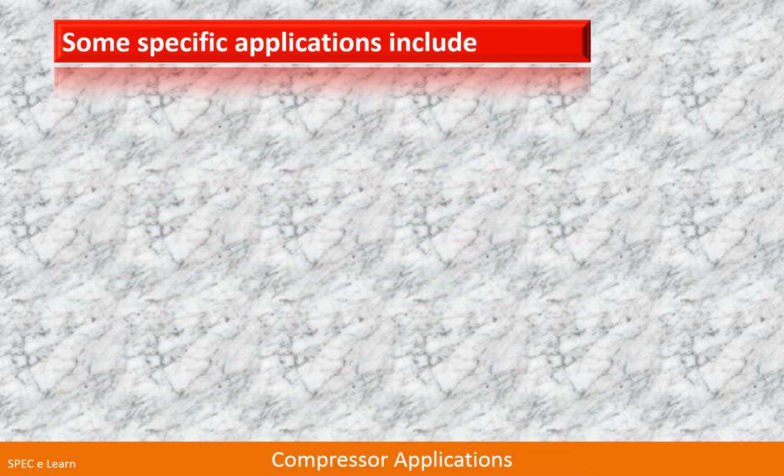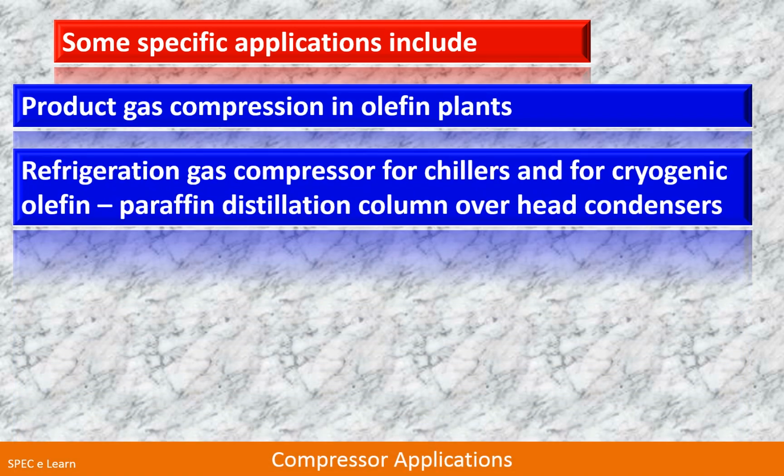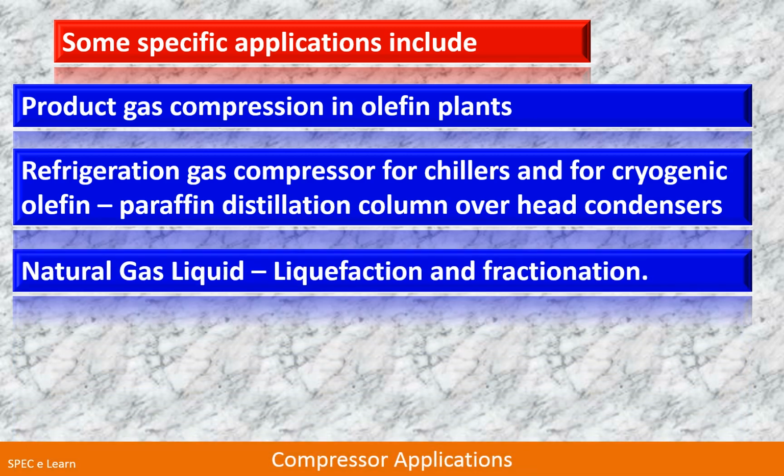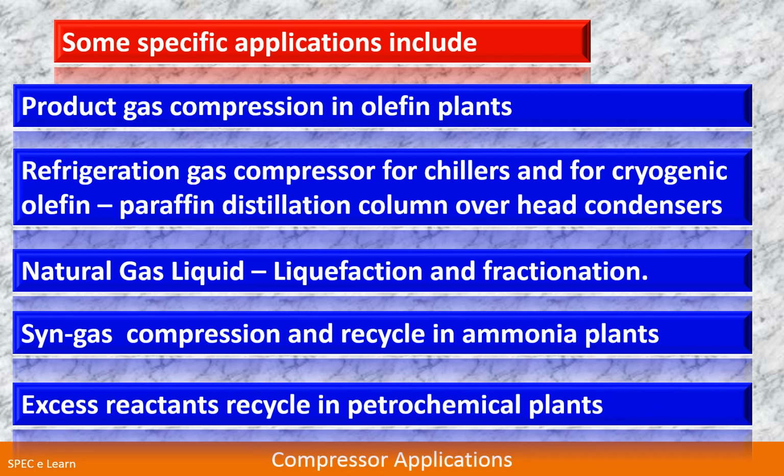Some specific applications in the industries include product gas compression in olefin plants, refrigeration gas compressor for chillers and for cryogenic olefin paraffin distillation column overhead condensers, natural gas liquefaction and fractionation, syngas compression and recycle in ammonia plants, excess reactants recycle in petrochemical plants.